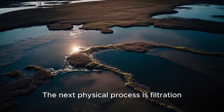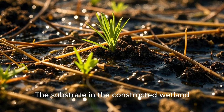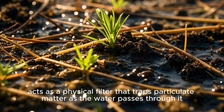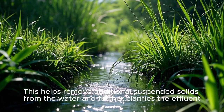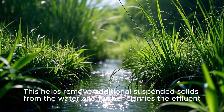The next physical process is filtration. The substrate in the constructed wetland, whether it's gravel, sand, or soil, acts as a physical filter that traps particulate matter as the water passes through it. This helps remove additional suspended solids from the water and further clarifies the effluent.